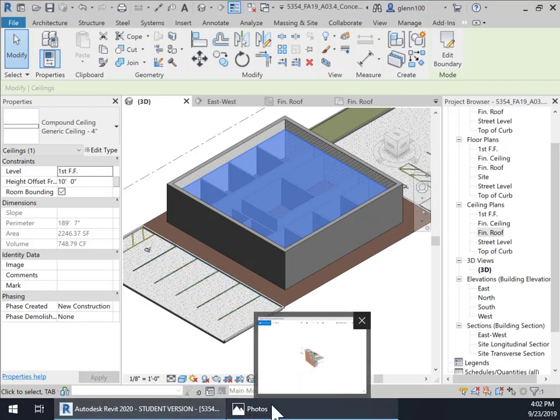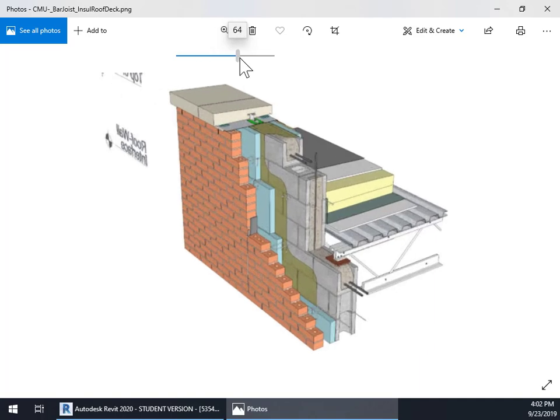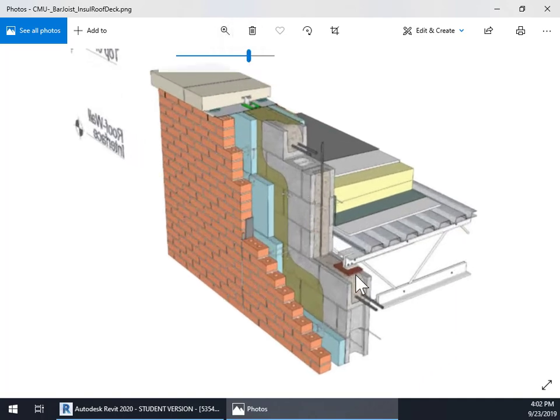Not that I have to know exactly what type of roof, but I predetermined in programming that the most logical roof structure type was CMU on bar joist, and then steel deck. A roof with steel deck and bar joist normally does not have concrete, which is used when you need to hold the loads of a floor, where the steel deck and concrete are put together.